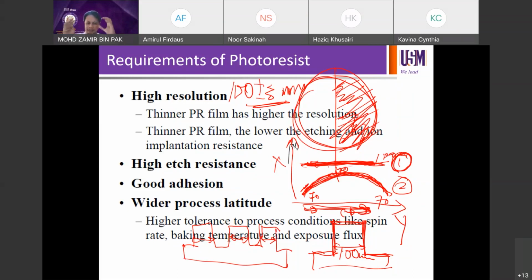Okay, but the essence I would like to tell you is the process window. That is the most fundamental thing you need to learn now. But when it comes to the real CD drift problem, it will involve many things. It can be the process, a specific module, the whole thing, scanner plus track, or just track. So when you troubleshoot, you will rule out one by one until you find the cause. So that's how it works as a process engineer or equipment engineer in a wafer fab.